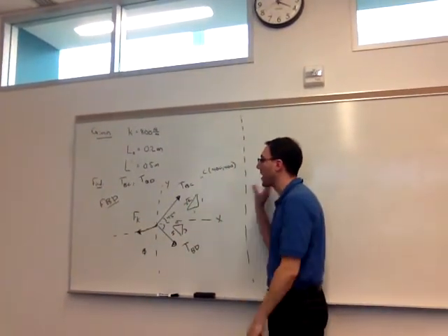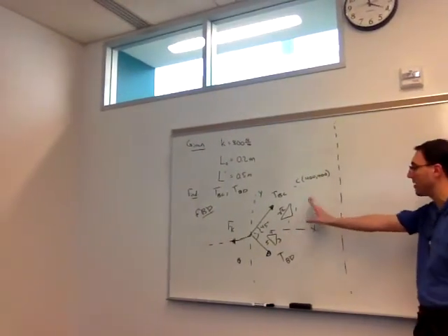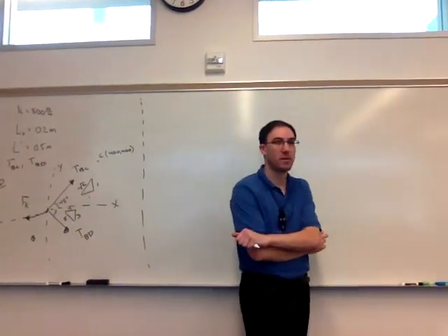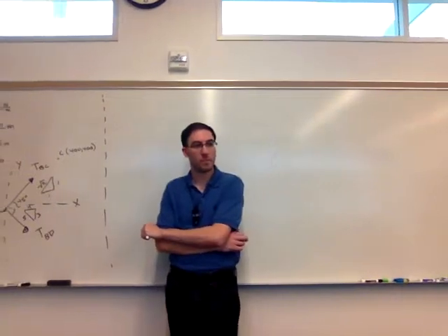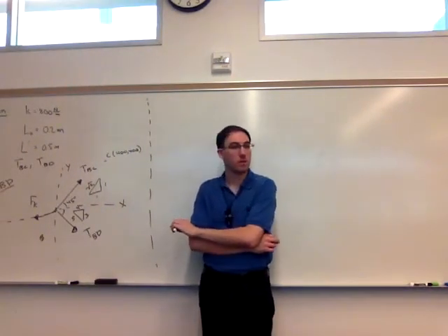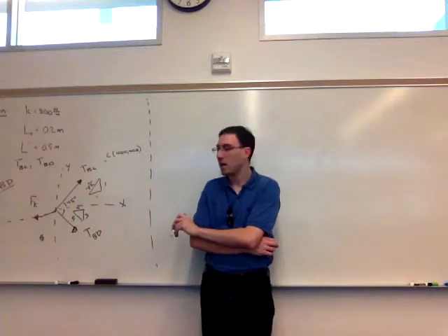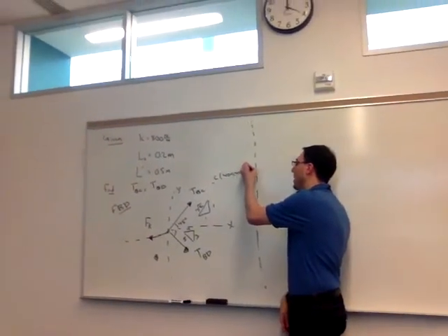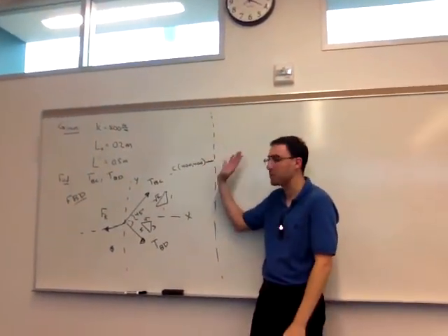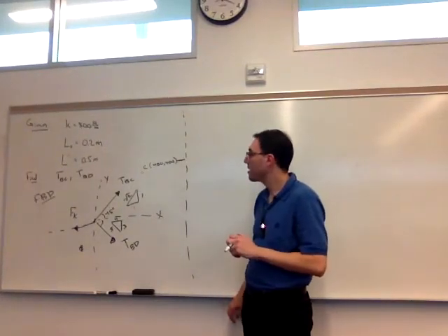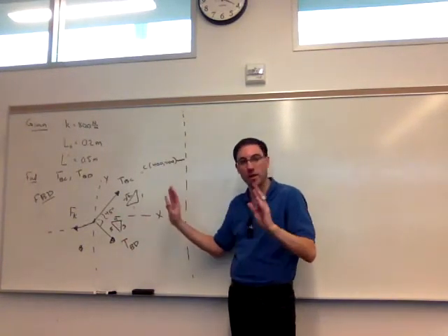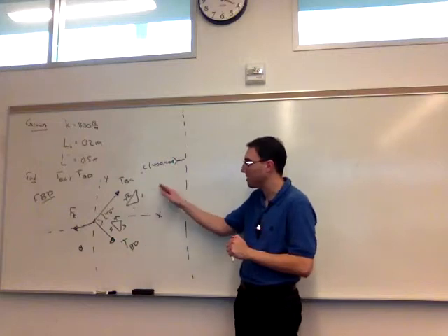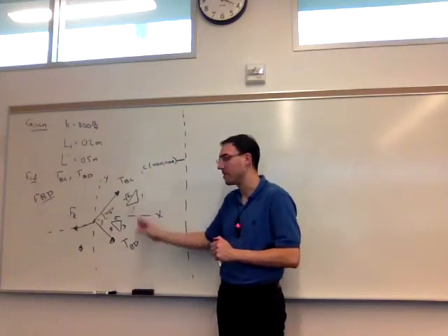So this is the complete free body diagram: labeled and dimensioned forces, our point of interest, and a full coordinate system. Any questions on any part of this free body diagram? Say we wanted to put the points up, like the 400 and 400 there, given maybe a different situation. Would it be okay to convert it right to meters? Right, yeah, I would say you're better off always converting, like I did here, to your base units. So if you wrote 0.4 meters, same thing. Anything else on the free body diagram? Again, one of the most important aspects of this class is being able to make a correct free body diagram. That is why it's basically a deal breaker on a quiz or an exam not to have one.